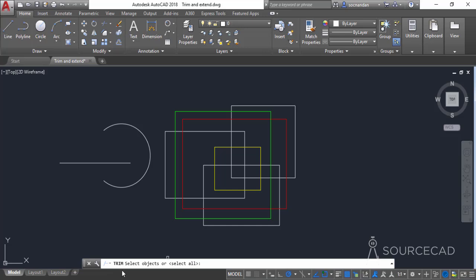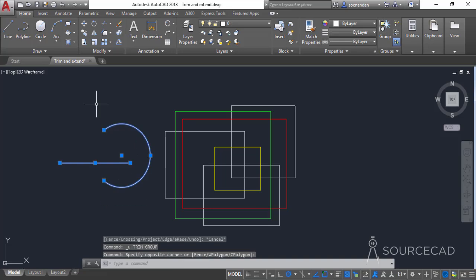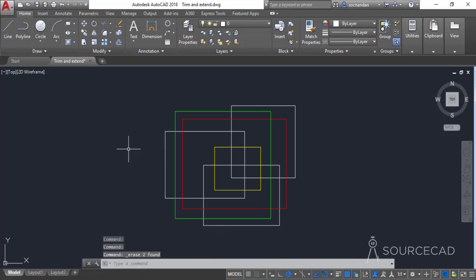Right now you can see that I've selected the trim tool, but now I'll press Enter. And now I'll simply press and hold my Shift key. Pressing and holding the Shift key will change the command to its next counterpart. And now I'll click on this line segment, and you can see that it's extending it even though we have the trim command active, and the similar condition will apply on the extend tool as well. So let's press Escape key and get back to the original geometry, and I'll also erase both of these objects. So this was all about the trim and extend tool of AutoCAD.